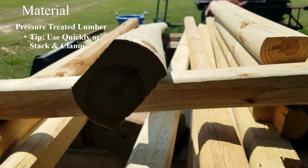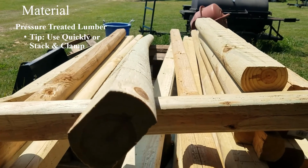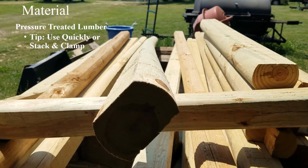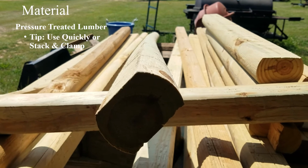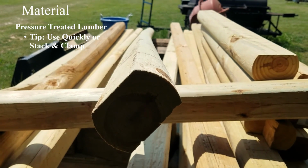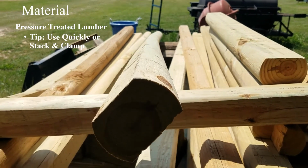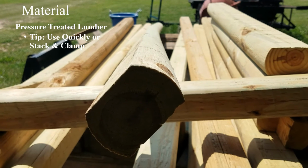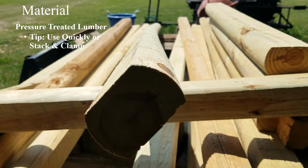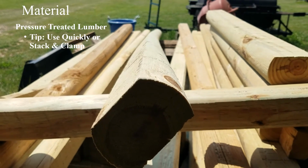One thing about pressure treated lumber is it will warp quickly because it's saturated with liquid, and then when it starts drying out, it'll start twisting. So you need to use it pretty quick, or you can stack and clamp it.